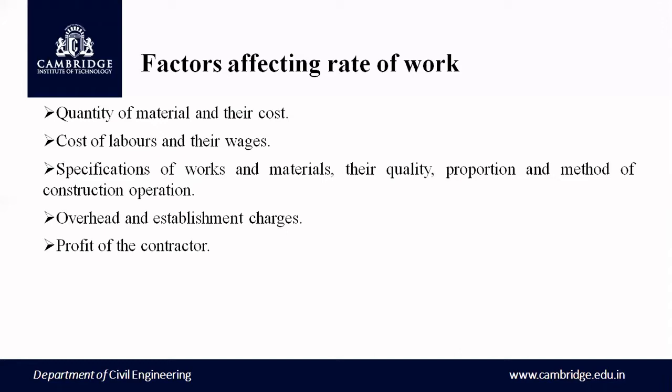Here, the labor charges can be obtained from the standard schedule of rates. And here, one more important point is that 30% of the skilled labor provided in the data may be taken as first class and the remaining 70% as second class. And the daily wages for the particular labor will vary.